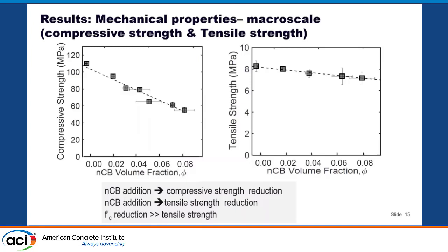No steel fiber here? No steel fiber, only plain? Yeah, it's plain. Okay, I just thought it was a fiber reinforced UHPC mix. So basically, if you can control the rheology, I think you may get a better result. This is why I was telling you we have to work on the dispersion and surface functionality of nanocarbon black. By that we can integrate nanocarbon black without the biggest problem. By the way, what is the particle size of your nanocarbon black? Like 30 to 50 nanometers. Okay, thank you. You're welcome.